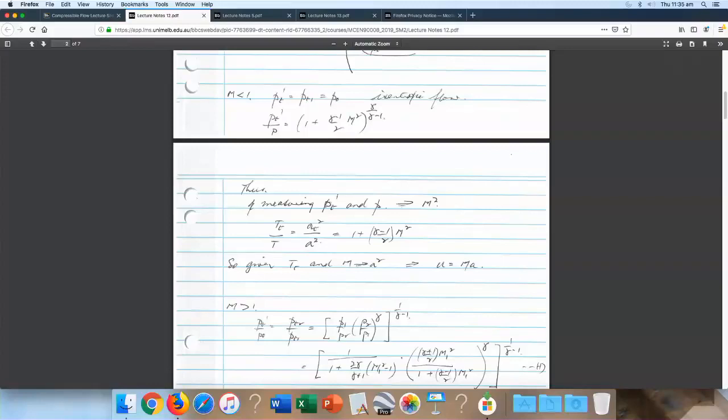But I'd have to be a bit careful now, because depending on this control volume, I've got an outside pressure that's not the same all the way around the body. I have an upstream pressure, but downstream through the exit area, I have a different pressure. So I better be careful for the whole volume.